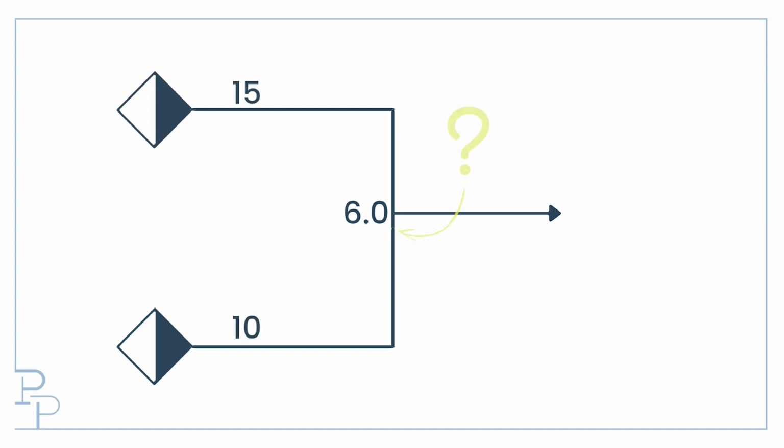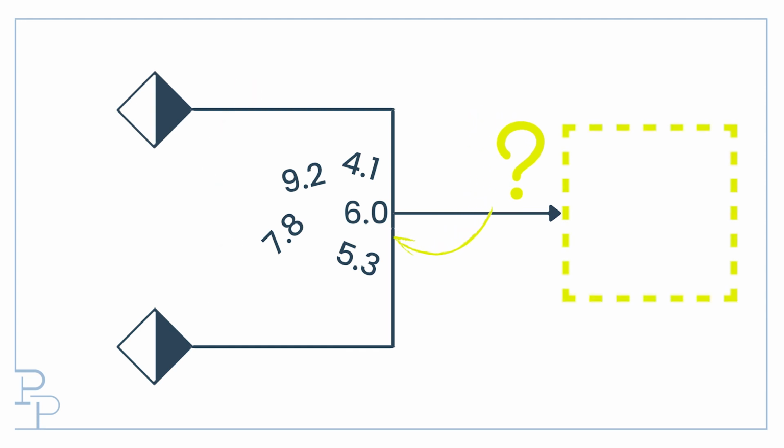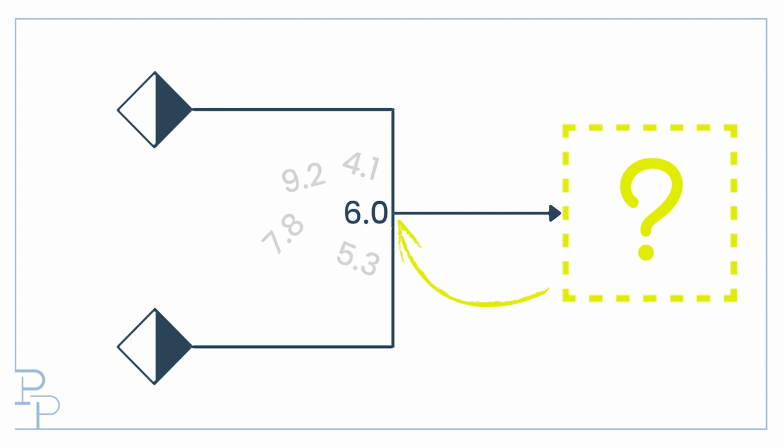Secondly, that mixing pressure, the pressure at which the two streams meet, cannot be determined by looking at the upstream pressures. Rather, it is determined by the system resistance downstream. If you don't know where the streams go, you can't really say at what pressure they'll mix. If you're designing the system, it means you'll be the one picking the mixing pressure.